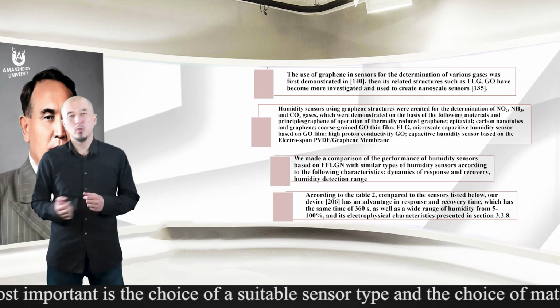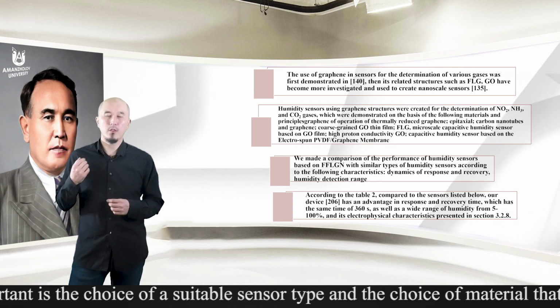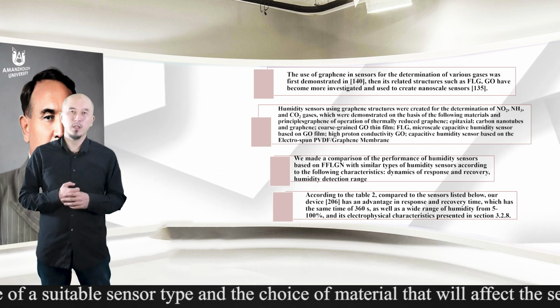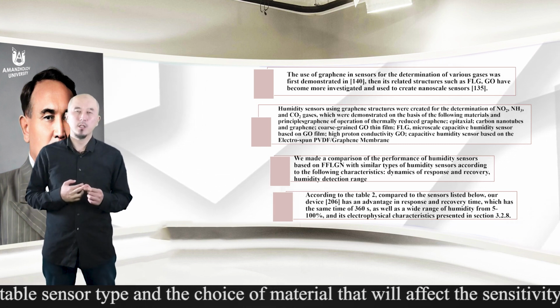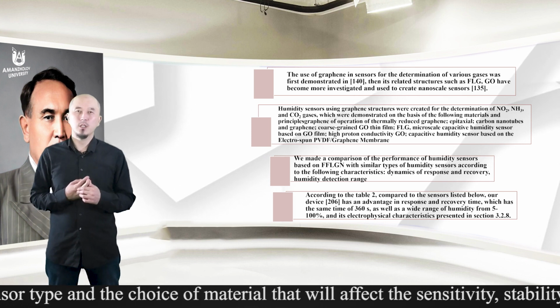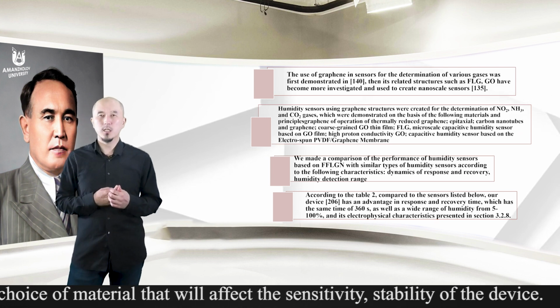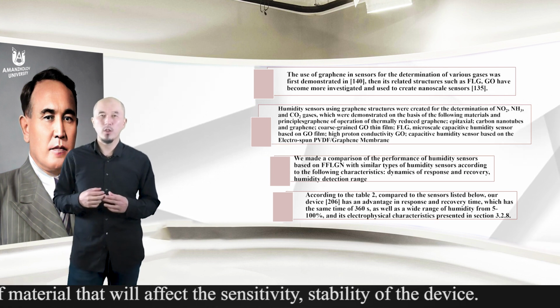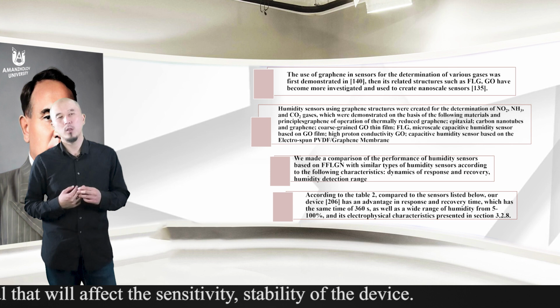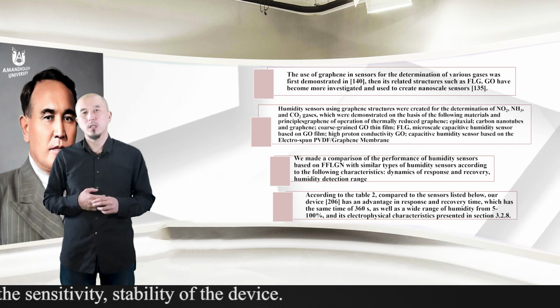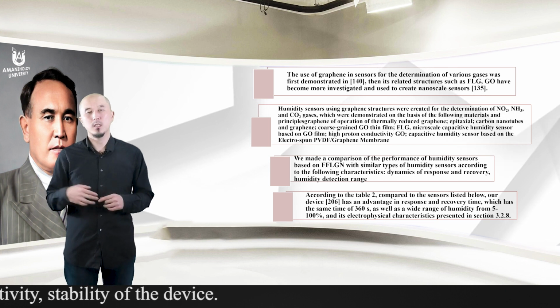Compared to the other types of sensors, our device has an advantage in response and recovery time, which has the same time of 360 seconds, as well as a wide range of measurable humidity from 5 to 100%, and its electrophysical characteristics are presented in the next sections.